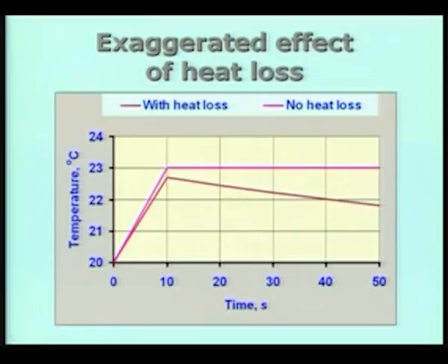Capital K into T minus T1 gives the derivative of temperature with respect to time. So, using this part of the process, I can in fact find out capital K. Capital K is nothing but the first order time constant of that system, which is getting cooled down. And if I can get the value of K from the cooling curve, that can be used in the earlier expression.